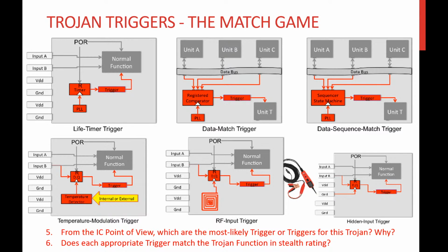So, as mentioned earlier, this Trojan is a complex unit attached to the data pathway. It is most likely that the data is being investigated between the RX MAC and the TX MAC, where the data is processed in its parallel and slower form and is not in packet form. The Trojan capabilities or payloads means that the data can be captured and compared, the data can be stored, the data can be modified, the data can be replaced, and the data can be reported as corrupted, whether it really is or not, or any combination of actions.